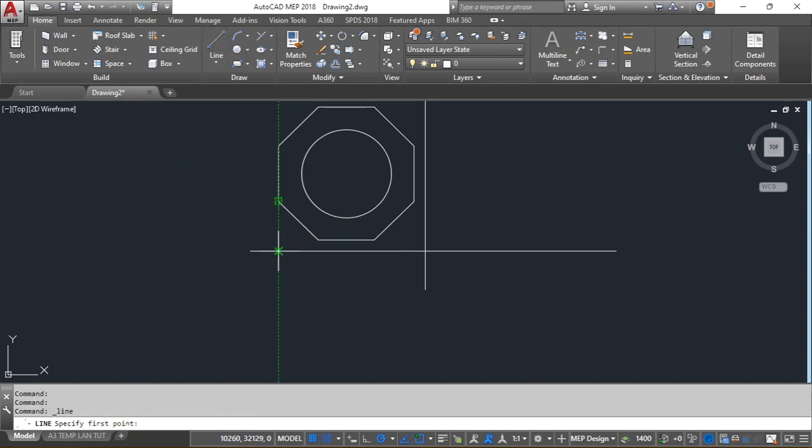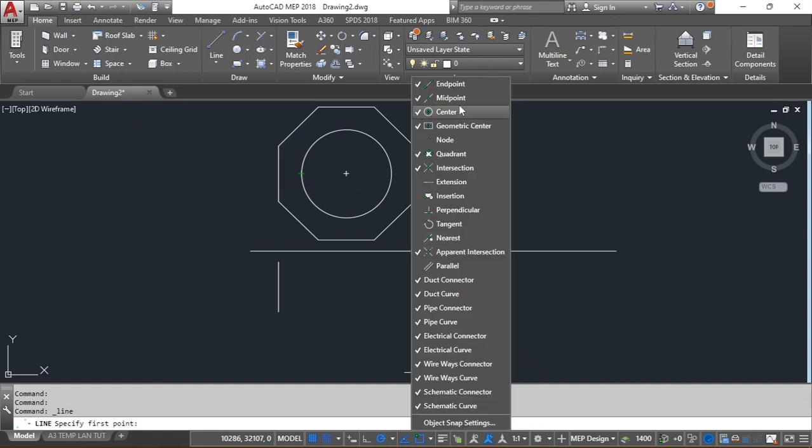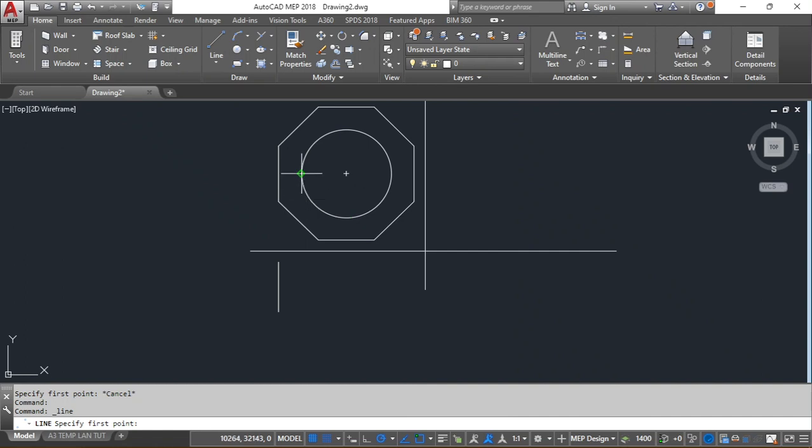Now we need to project lines down here to create the plan. Pick an endpoint. We're going to start off from somewhere there and draw the first line. Then click the line tool again. Make sure quadrant is activated under object snap settings so that you can pick off points of the circle. So along that line, I'm going to start off there.